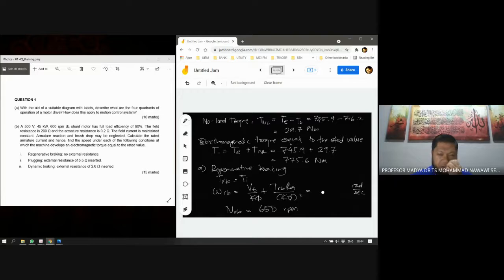Remember, just now we have omega. You still remember the top speed here. So we have point 0.1, 0.2, 0.3. So point here, 0.1 here, you have 600 RPM. And now, during regenerative braking, you have 650 RPM, slightly higher than the speed at omega 1, condition 1, point number 1. You can also calculate for point number 2. And so that's why the speed during the regenerative braking is 650 RPM.